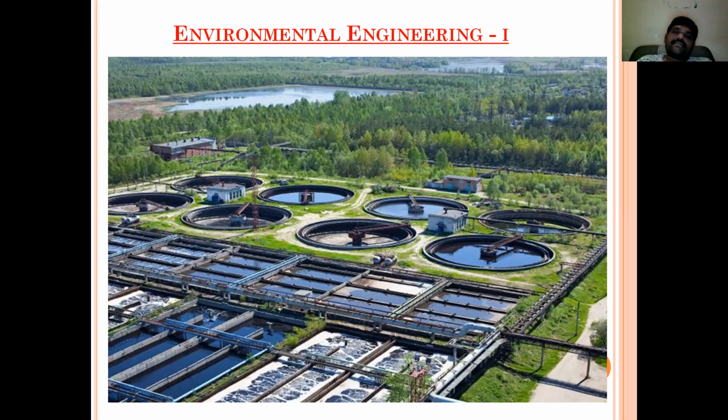We have finished 2 stages of treatment: sedimentation, followed by sedimentation with coagulation, where we have seen the removal of weighted particles and also removal of fine colloidal particles with the help of coagulants. Now we are in filtration, and here we are removing